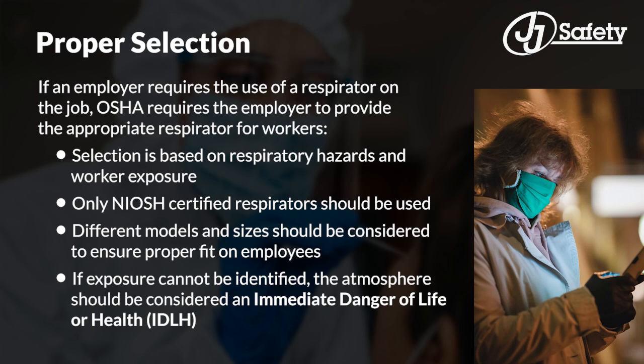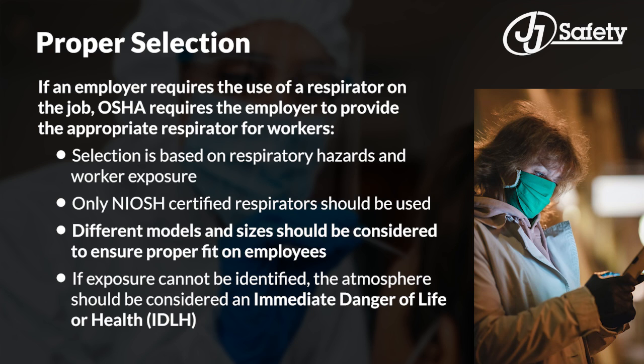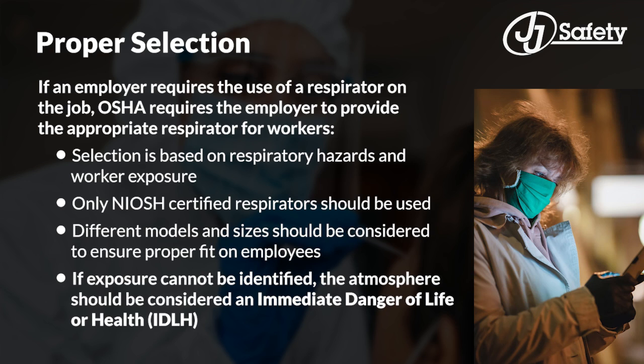Proper selection. If an employer requires the use of a respirator on the job, OSHA requires the employer to provide the appropriate respirator for workers. Selection is based on respiratory hazards and worker exposure. Only NIOSH-certified respirators should be used. Different models and sizes should be considered to ensure proper fit on employees. If exposure cannot be identified, the atmosphere should be considered an immediate danger to life or health, IDLH.